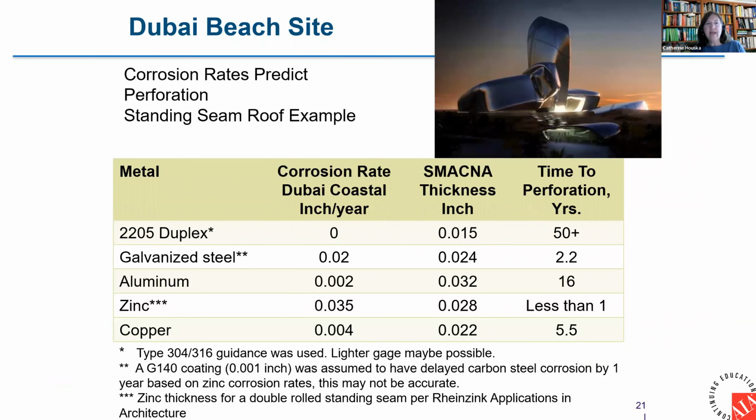There is a great deal of data that's been collected around the world documenting the relative corrosion resistance of different stainless steels. This happens to be data from Dubai. Parts of the Middle East are extremely corrosive with high levels of salt deposition, lots of fine particulate in the air, and while the average humidity is low at night, there is enough so that water accumulates on surfaces. And that combination of very little rain to wash away the accumulations, but enough to certainly dampen them at night, creates a highly corrosive situation.